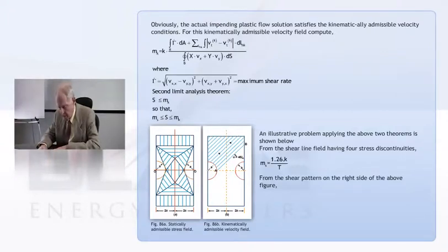On the velocity picture, it's usually easy to select these velocities. And in fact, if you think back to using the minimum potential energy theorem in elasticity, you can always dream up some kind of displacements that make sense to you. Well, this one is really dead simple. What you do is you take a line at 45 degrees, because if I have uniform tension above and below, then the angle for my shear line is going to be 45 degrees to that axis.